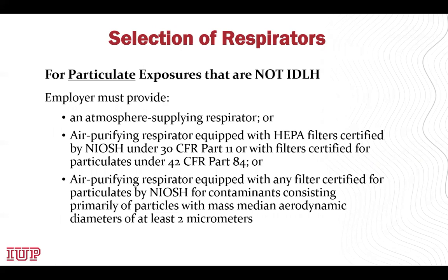For particulate respirators that are not IDLH, the employer must provide an atmosphere supplying respirator or an air purifying respirator equipped with a HEPA filter certified by NIOSH under 30 CFR Part 11, or with a filter certified for particulates under 42 CFR Part 84, or an air purifying respirator equipped with any filter certified for particulates by NIOSH for contaminants consisting primarily of particulates with a mass median aerodynamic diameter of at least 2 micrometers.